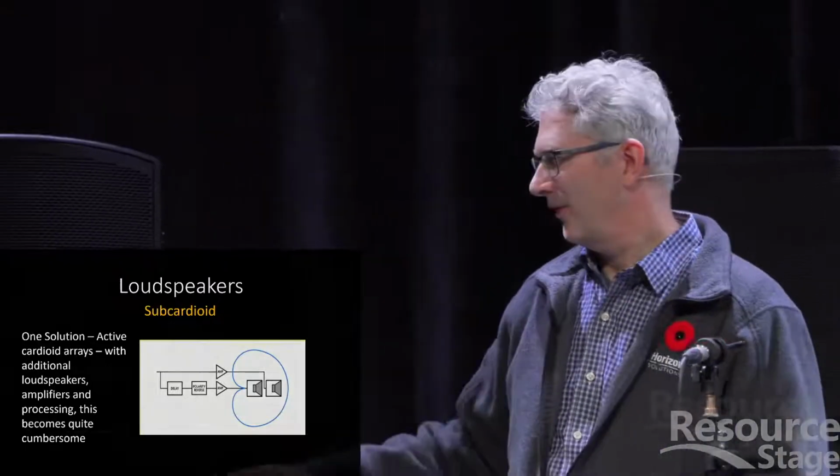But the first one that he created looked exactly like this, only it was a standard conventional loudspeaker, the CX12. Really compact. It's got a 12-inch woofer in it, and then a coaxially mounted high-frequency driver right in the front. That high-frequency driver is available in a number of different dispersion patterns. This particular one is 90-degree horizontal and 45-degree vertical.